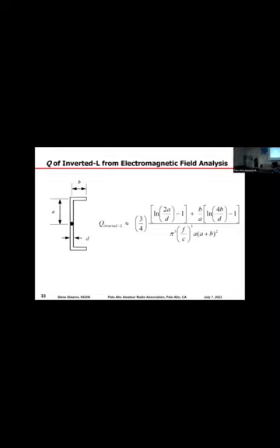Or you could call it a droopy dipole. Some people like to call this the droopy dipole drawn vertically. So it's a dipole where the ends bend down. You can also put it over an infinite ground plane and call it an L over a ground plane. And so we have another slightly more complicated formula, but again, it depends on all the geometrical parameters. In other words, the shape of the antenna and some constants. Speed of light, pi, natural logarithm pops up in two places.